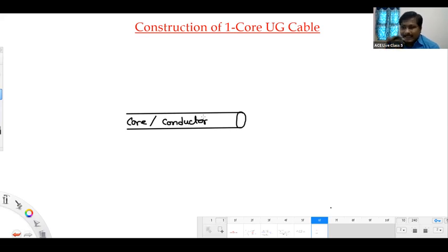The material might be aluminum or sometimes copper; that doesn't matter. But what I am asking is, what type of conductor? Is it a solid conductor, or AAC, or ACSR? AAC we have to use, to reduce the skin effect and the proximity effect. You need not go for ACSR. So it is an AAC conductor we have to use.